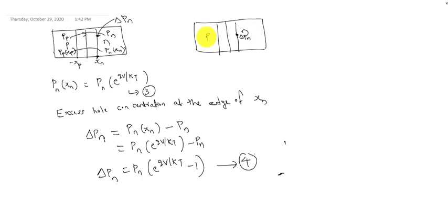Np is the equilibrium value on P side, minority carrier. Similarly, with the bias, more number of electrons will diffuse from N to P, and that value is represented by Nn of Xn, and the value here will be Np of Xp, electron concentration on P side.